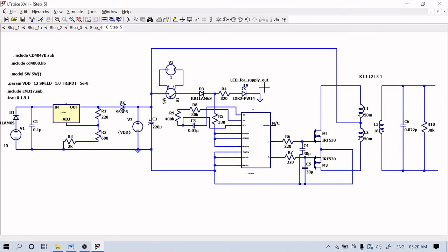Again I will say, here it is a solar panel circuit. This is a voltage regulator part, and this charging unit is coupled via this Schottky diode. This is your switching line, and because of the switching line only, this inverter circuit point is biased. The output of Q and Q bar is fed to these MOSFET drivers, and the output from the drivers is passed on to the driving winding, and it is finally coupled to the second winding. These capacitors and resistors are used to shape your output to 30 volt, so that some spikes will be reduced.